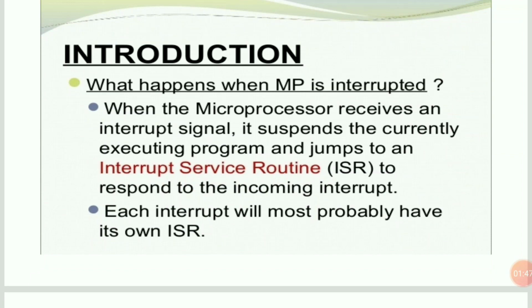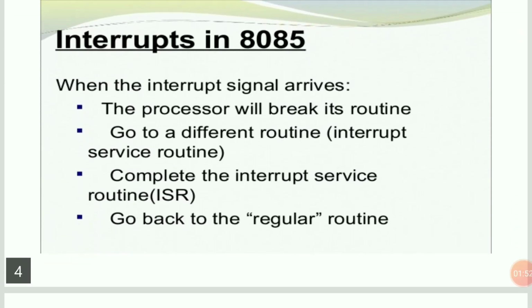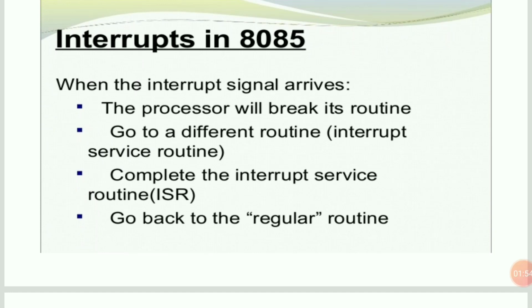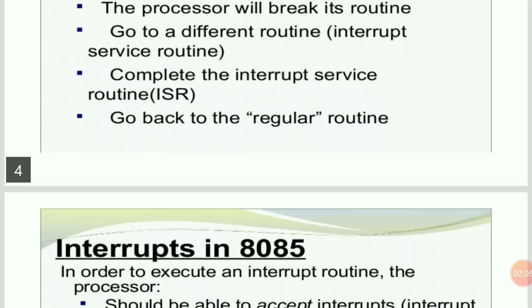Each interrupt will probably have its own ISR. When the interrupt signal arrives, the processor will break its routine, go to a different routine, that is the interrupt service routine, complete the interrupt service routine, ISR, and go back to the regular routine.